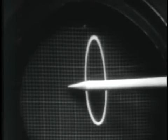Remember, ER is greater in amplitude than EC. Since I have ER applied to the vertical deflection plates and EC applied to the horizontal deflection plates, we will have an oval at 90 degrees rather than a perfect circle. So we have two voltages 90 degrees out of phase with the amplitude of one greater than the other, or ER is greater in amplitude than EC, and the two voltages are 90 degrees out of phase.